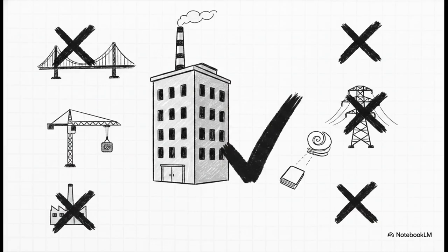It provides general guidance. If you're designing highly specialized structures like bridges, towering chimneys, heavy-duty cranes, transmission line towers, or cold-formed light-gauge steel sections, well, IS 800 steps back. Those require their own highly specialized standards. Plus, while it tells you how to design the steel itself, it only gives broad guidance on the actual loads. For specific dead, live, or wind loads acting on your building, it's going to direct you to reference IS 875.